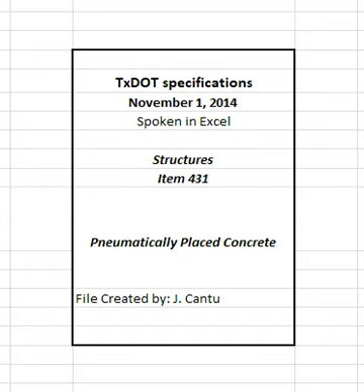Encase completely each layer of wire fabric in concrete that has taken its initial set before installing the succeeding layer of wire fabric. Place the reinforcing fabric parallel to the finished surface, and support it so it will be at least 3/4 inches out from the surface to be covered.